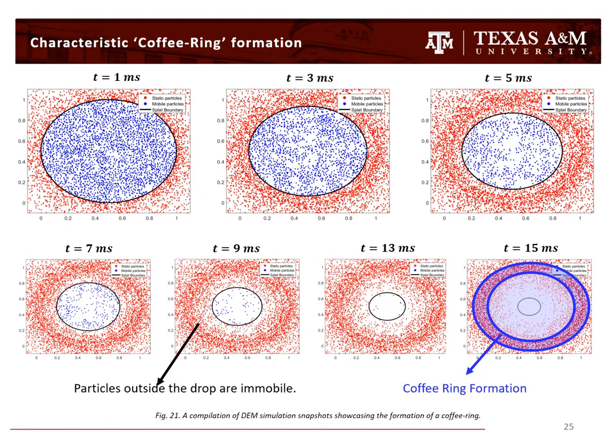As a result of particle aggregation and the simultaneous evaporation of the droplets, we get something called the coffee ring effect, which is very characteristic of spray coating systems. So basically the particles start to aggregate, and as the droplet starts to evaporate, the particles become deposited at a boundary. And as time proceeds, you can see they form this ring formation, which is called a coffee ring formation, which is very frequently seen in different spray coating processes, and is an essential feature of this model that we can predict it close to reality.